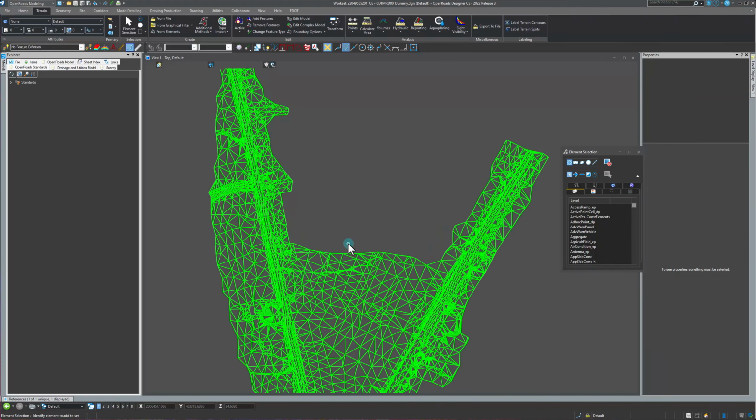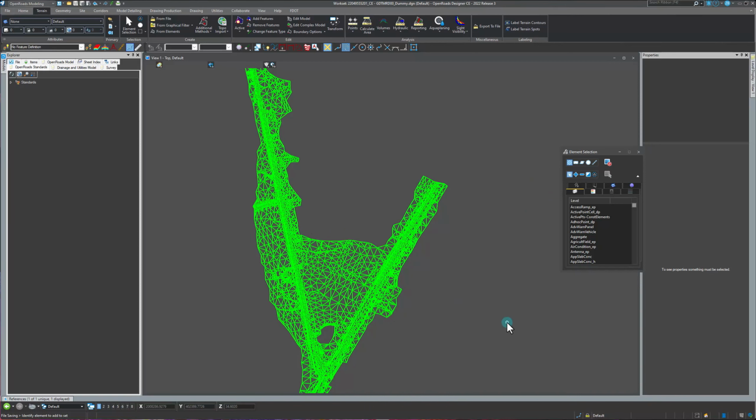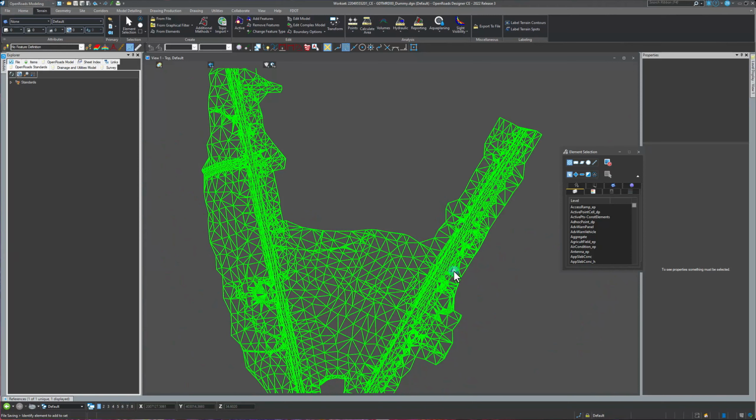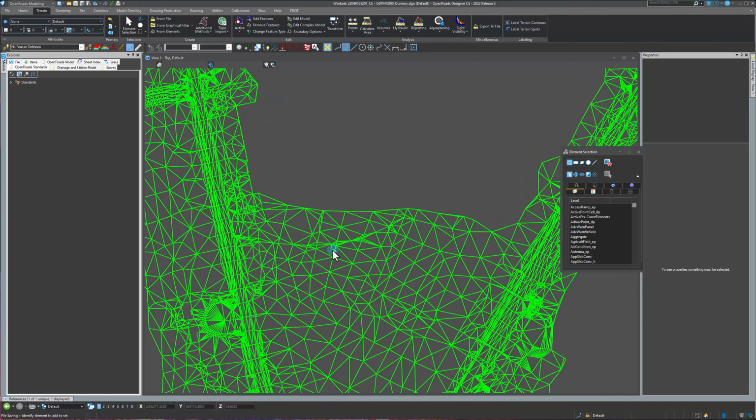So the way that I learned this from Bentley was to create what they called a delta terrain model. They basically offset this terrain 0 feet. And so you've got basically two terrains that are exactly the same that you're complexing together. My thought was, why do you need that big of a terrain to complex together if all you're really doing is creating an extra dummy terrain just because a complex terrain model requires two terrain models to form it?